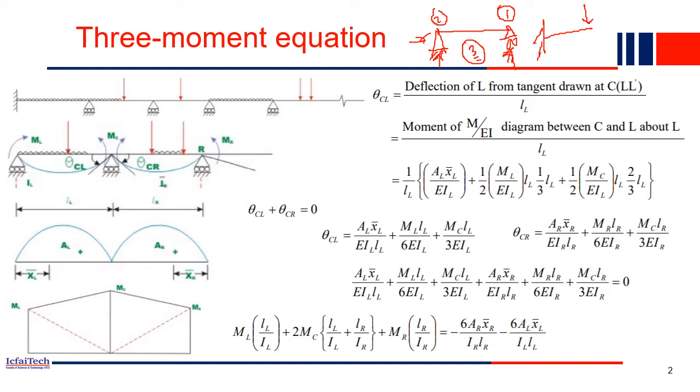So easily we can compute all the reaction forces, and we can draw the bending moment and shear force diagrams. We can calculate the slopes and deflections after application of the load. Everything we can do within this simple structure. Similarly, a cantilever beam is also a determinate structure, because its unknown reactions are 3, and we have three equilibrium equations. So using this, for any cantilever beam we can calculate the shear force, bending moment diagram, slopes, deflections, anything.